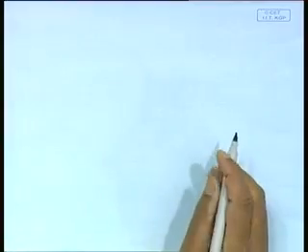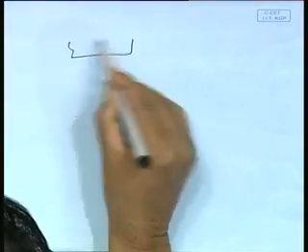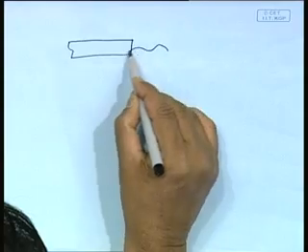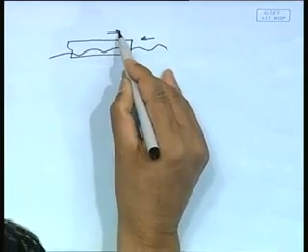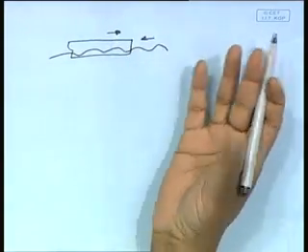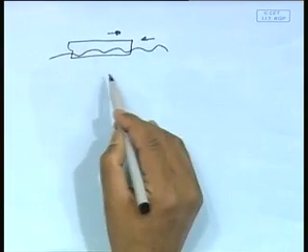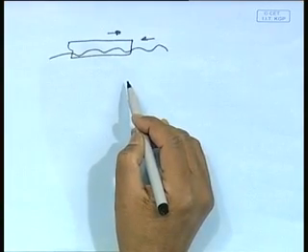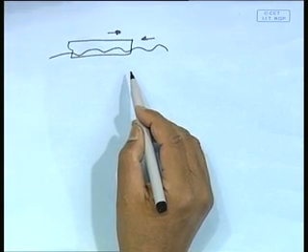Now, the other thing is, when is it most important for added resistance to occur? Obviously, it is most significant when head waves are coming. Waves are here and the ship is going here. In fact, that is the only time that you would expect very large heave and pitch and very large added resistance in a head wave. You expect much larger added resistance in a head wave condition.